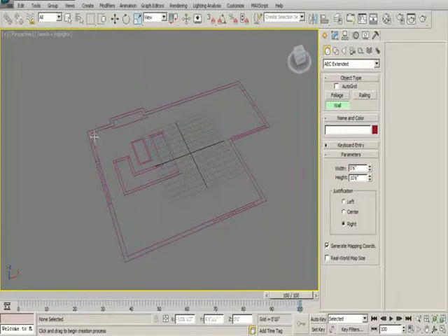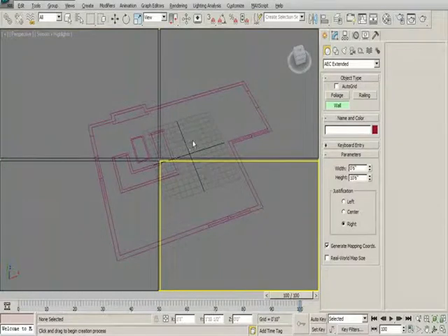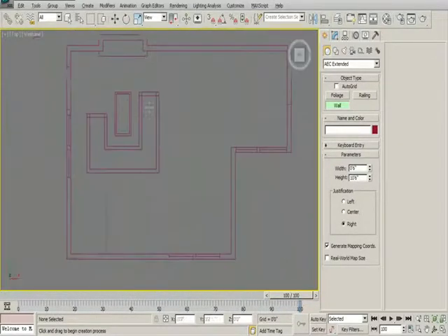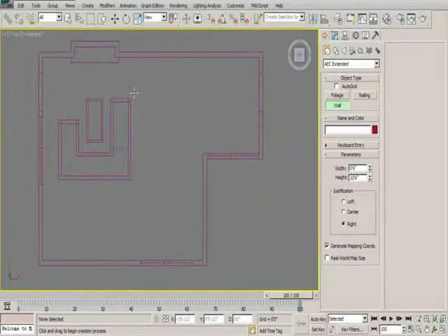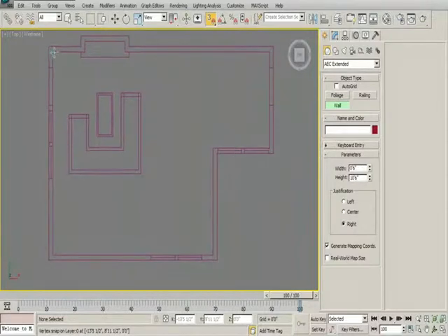If you are modeling on the internal spline, you should choose left, but I go with right. So let's go to the top view and enlarge that, and make sure your snap option is on. Right click on it, and you should choose vertex while working with splines. I can see it's snapping with my vertices.